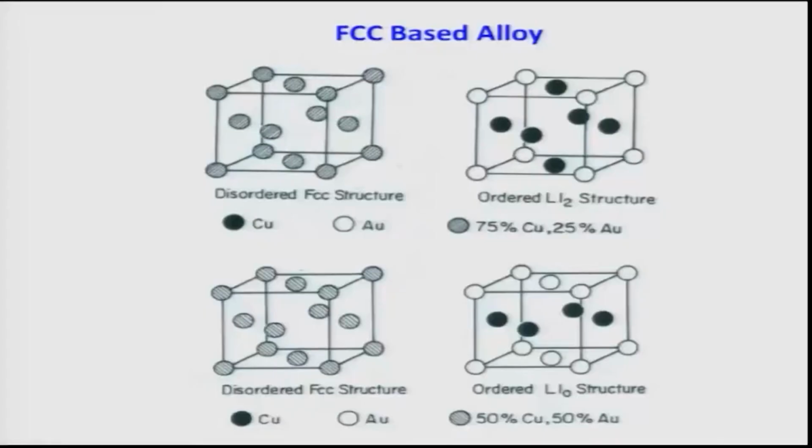Okay, let us give examples of that. Just now I told you about the alpha to Cu3Au structure. So, in a disordered solution, which is the high temperature alpha phase, as you see here, there is no specific position where specific atoms can go. It is an average situation, like the cube corner or face center positions can be occupied by either copper or gold atoms. There is no specific way of demarcating that.